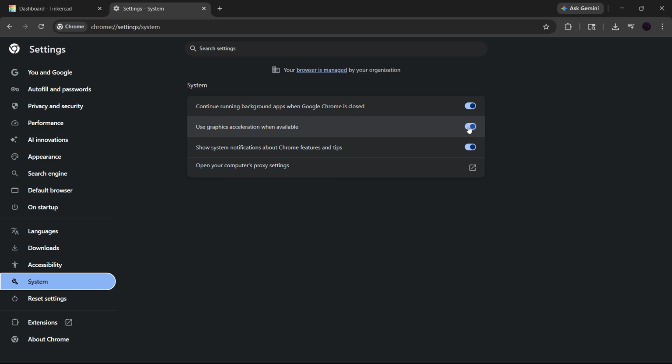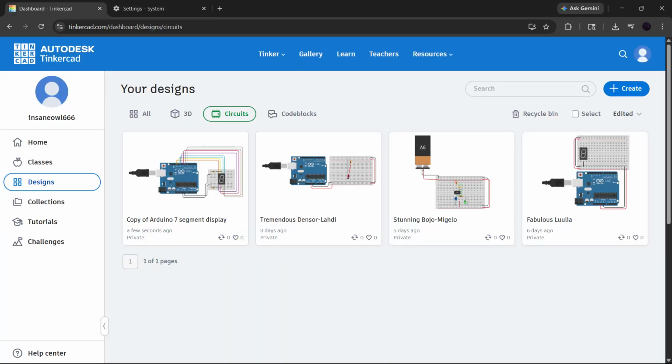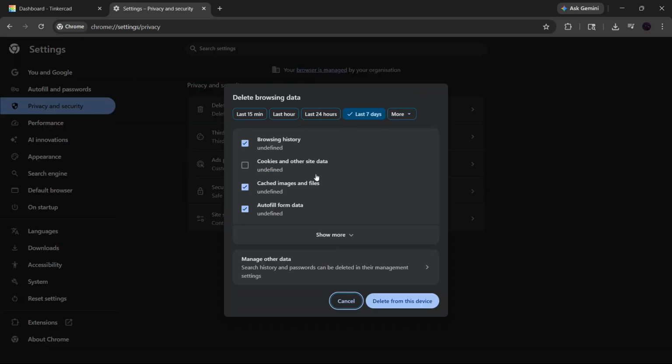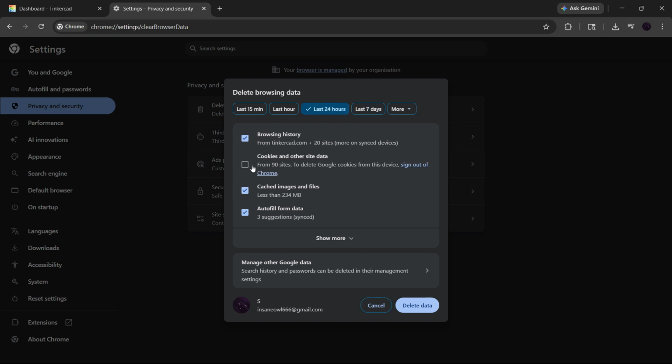So to quickly recap, check for short circuits, simplify your code, add delays, fix floating components, reset complex parts, duplicate the project if needed, and clear up browser memory. If you go through those steps one by one, you'll usually find the cause of the Tinkercad Circuit Simulation Failed error pretty fast.